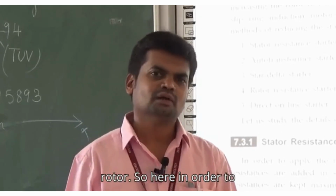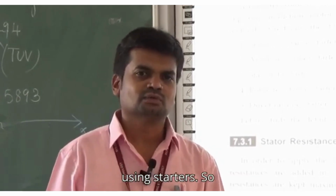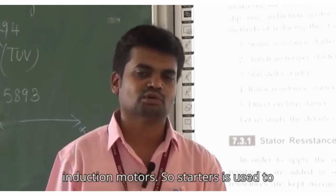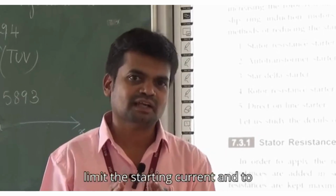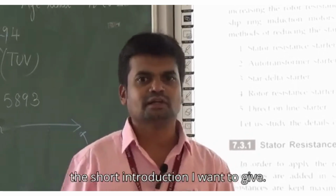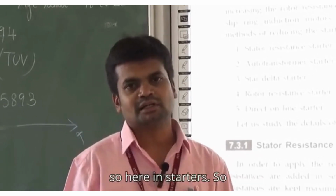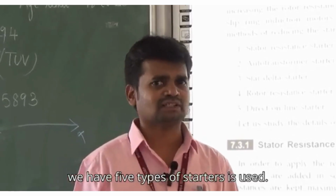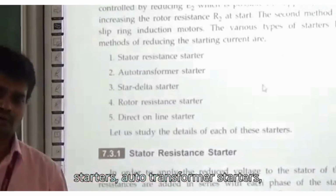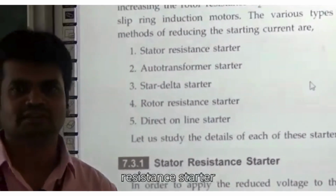Here, in order to rotate the induction motor, we are using starters. Starters are not only for rotating the induction motor, they also protect it. A starter is used to limit the starting current and to protect the induction motor. This is the short introduction I wanted to give before entering the starter options. In starters, we have five types: the first one is stator resistance starters, then auto transformer starters, star delta starters, rotor resistance starter, and the last one is DOL starters.